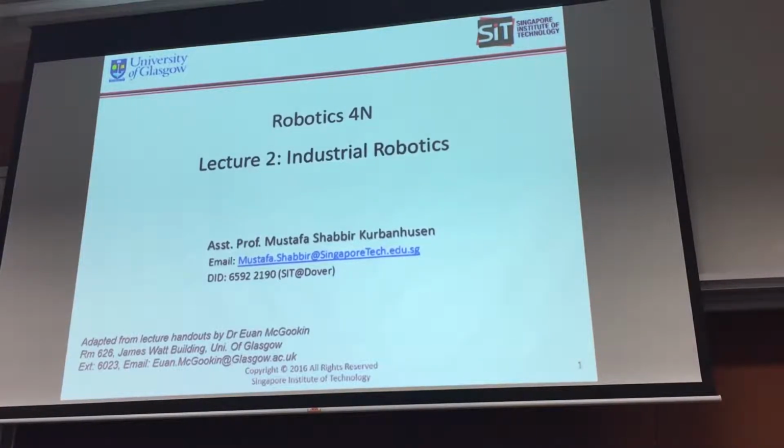So everything is between what the controller knows in its virtual world and the real world. There are a lot of offsets that you will get, and you will need to do all this calibration or fine-tuning to make it work right. It's not so straightforward to just put the robot there and start. So these are the things I want you to bear in mind for industrial robotics.